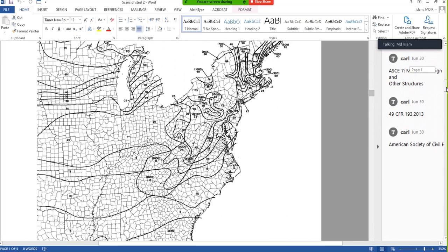The second part of this figure is the east side. Here, New York. And where is New York? Here maybe. I don't know. Here, I can see this is Long Island. New York is here. This is the tail. Tail means Long Island. Albany is somewhere here. Buffalo is somewhere here. Okay, so you can see a lot of data is given. Say Buffalo close to Niagara Falls is 60 PSF. New York, Long Island, I can see 25. New York City, 25 PSF.